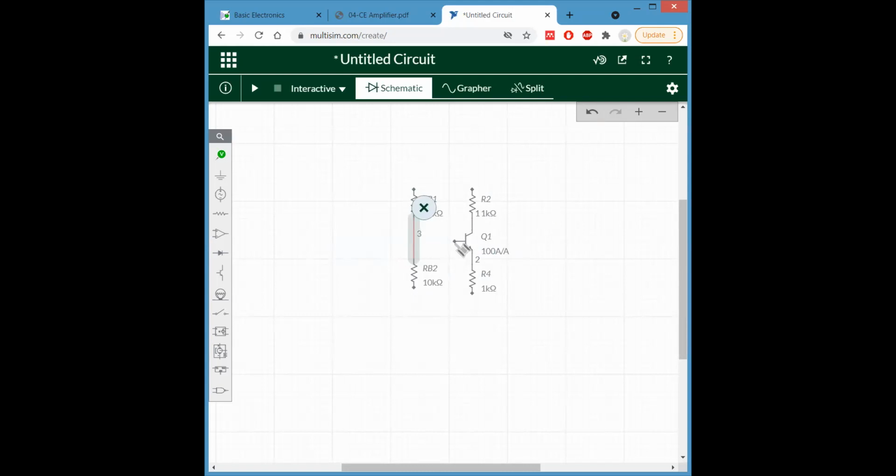As they are base resistors, we are connecting the base. Now the collector one, we should rename it as RC. The value we have considered over there is 4k, and the emitter resistor, that is RE, we have considered as 1k.